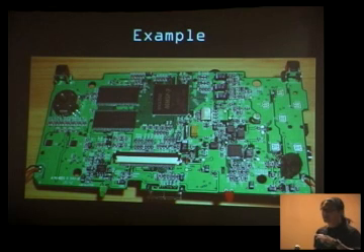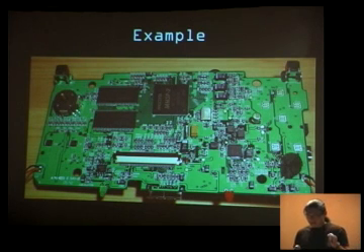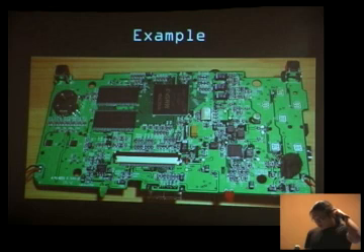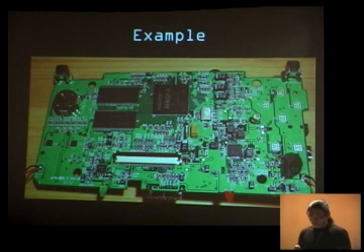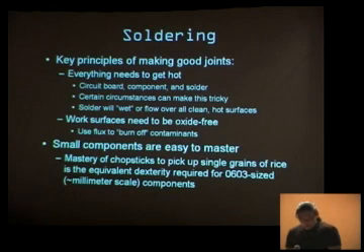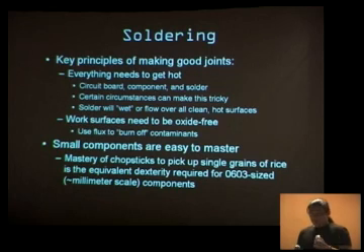And I didn't actually look at this ahead of time. I'm just telling you, based upon having looked at enough of these, that's what they're doing, right? Eventually, if you look at enough boards, you have enough of the schematics in my head that if you told me we want to modify this because we have to work with a different LCD, I can tell you, well, okay, here are the signals for the LCD controller. Here are the signals you've got to look at for the LCD bias, and then you can go with it from there. So that's sort of the art of looking at boards and static analysis.